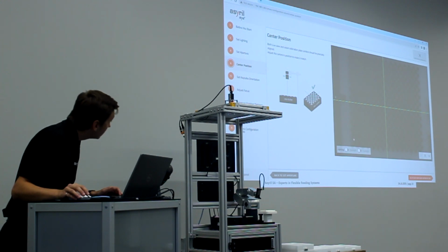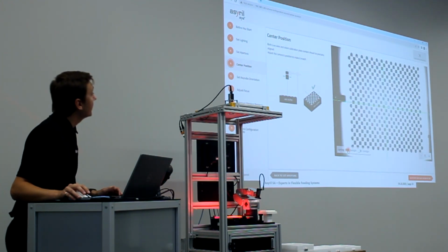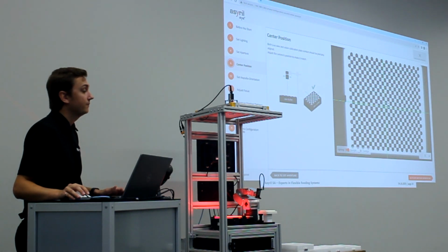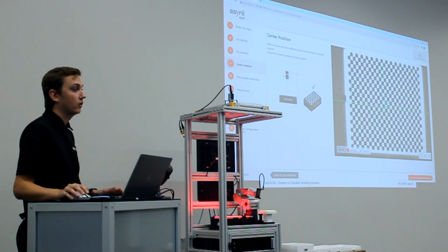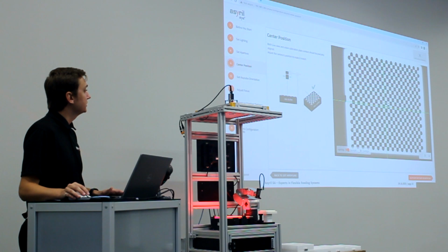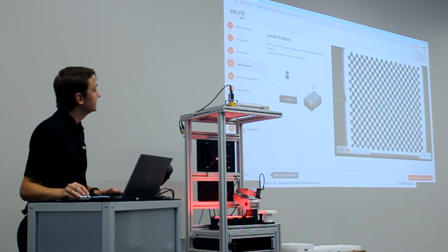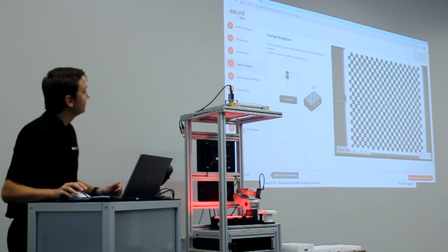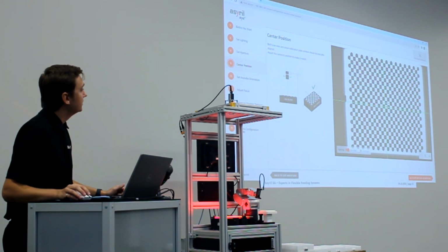I lost my mouse. So if we do the backlight, you can turn it on. We had just moved this from a trade show. So every time you move the iPlus camera or move the whole unit, you should probably redo vision calibration, as things will get moved. So you can see it's not lined up here, and we'll leave it for now. But you would essentially center it in between these four circles here, right about here.